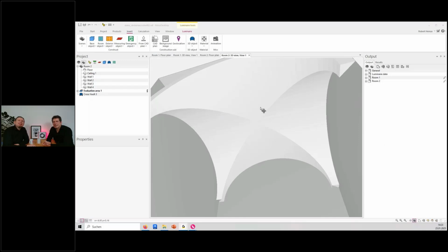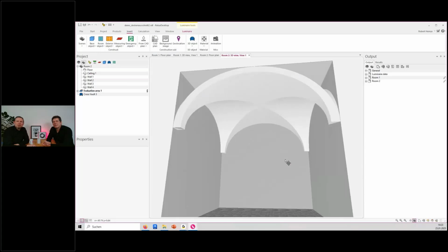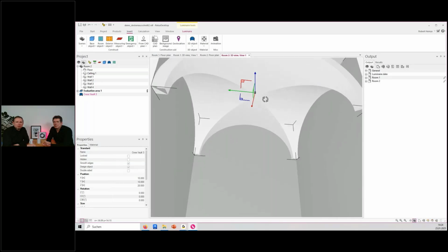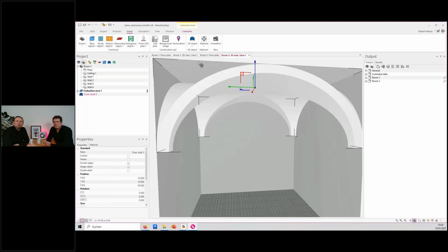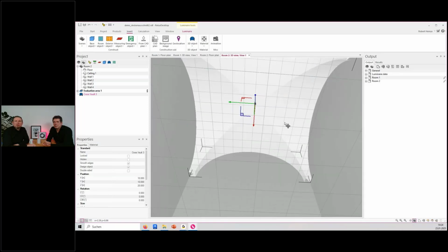And the limitation, as said, is that it is not possible to select these as a ceiling object, not yet. So that means luminaires will just be included into the geometry. They will not be cut out. But for the rest of the features, you have all the material stuff. You can also calculate correctly with these kinds of ceilings. And you just have to be aware that the room height should be the maximum of your 3D constructions, and then you model against the ceiling.